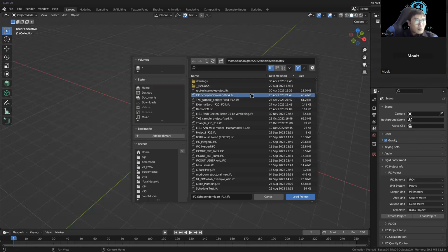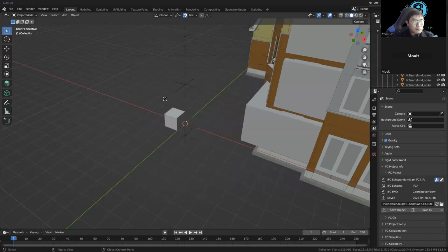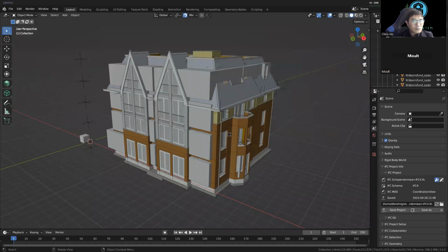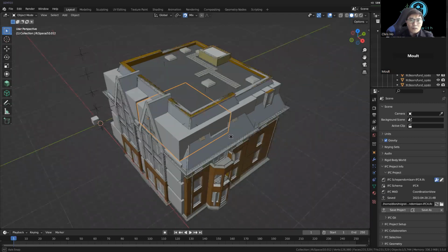So maybe this model here. This one comes from ArchiCAD. It doesn't really matter what it comes from. You can edit relationships and properties and non-geometric information relatively safely, I'd say. And the reason I say that is because the non-geometric data that comes from proprietary tools is generally not too bad. The geometric data that comes from this software sometimes has problems with it, which restrict the way you can edit it.